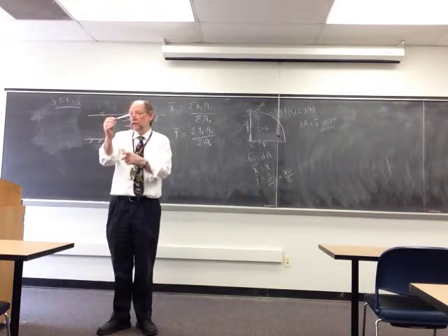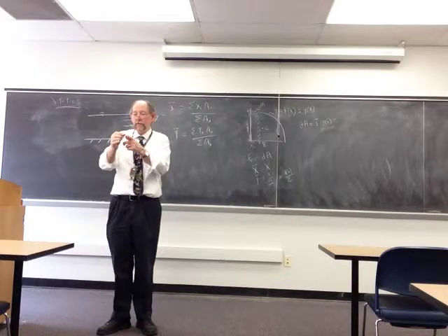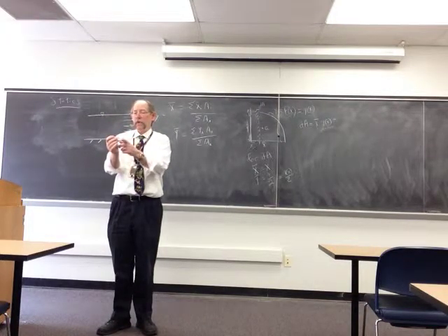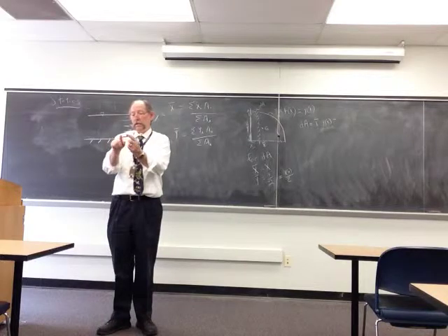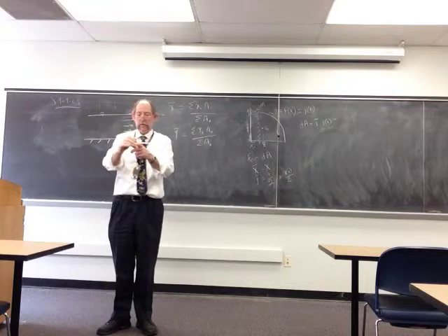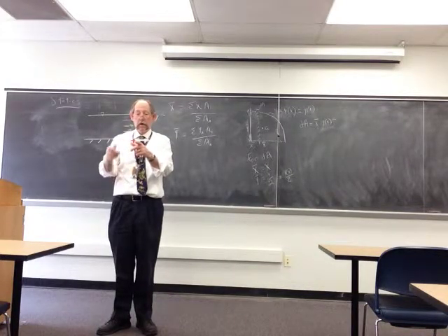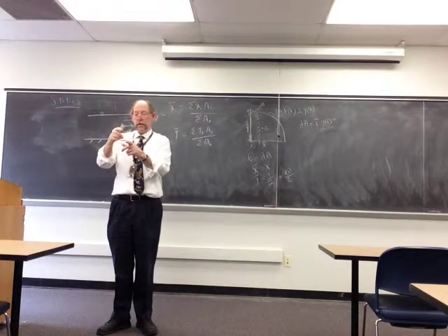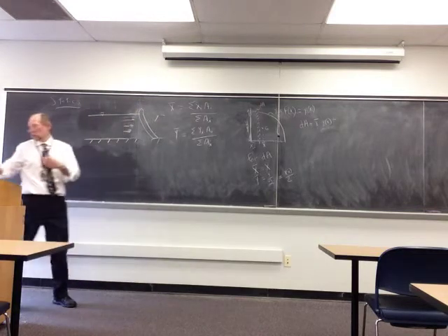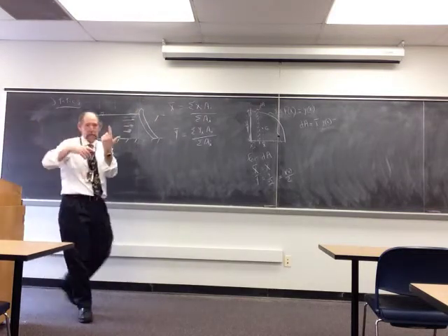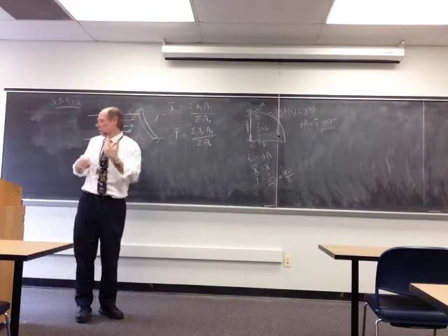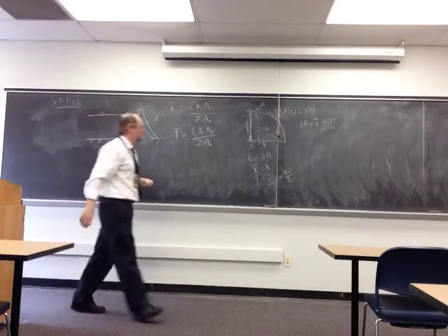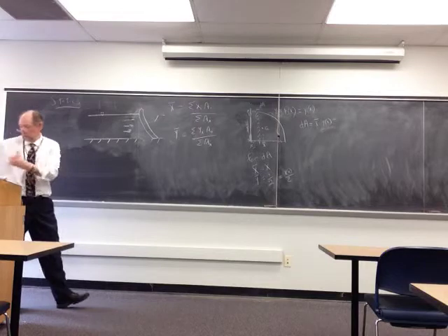If you're going to balance this thing on a single point, it's got to be on its center of gravity. You might look at the pen and say it's at the halfway point, but it's not, because the tip is heavier with the ballpoint and all that extra plastic, so you have to find it someplace in there. It's not going to let me do it now, kind of like that. So the center of gravity is someplace towards the front of the pen, not quite in the middle. That's another way to think of the center of gravity: if you take this object and balance it on a point, you have to balance it on the center of gravity for it to stay balanced. All right.